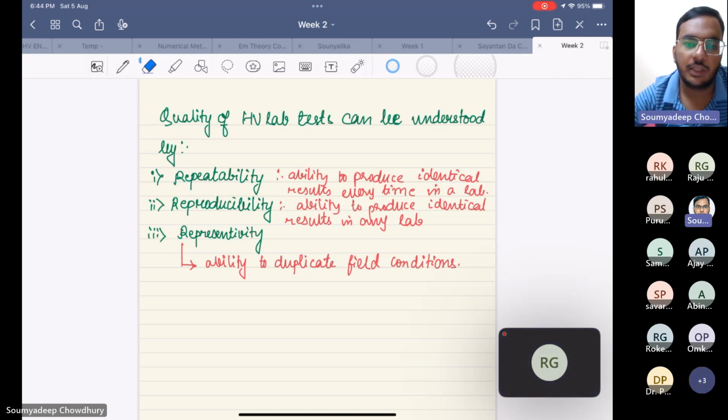The thing is actually, when we do it, if it passes the test or if it doesn't flash over, there is no significant deterioration in the condition or the performance of the insulator. So if it is withstanding this 20 kV, in one particular set of experiments we'll do it for say 10 times. And again, tomorrow we will do it for another 10 times.